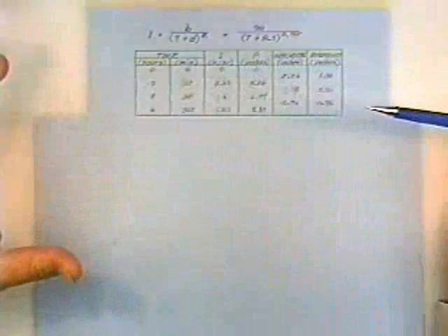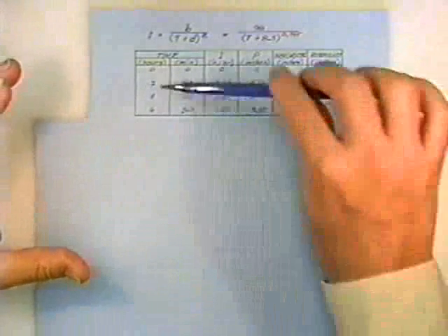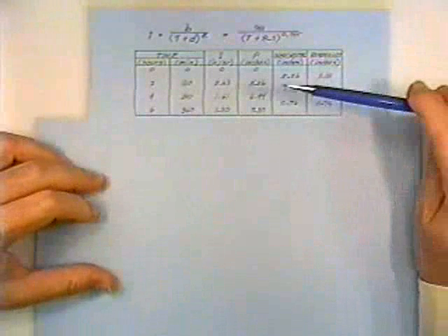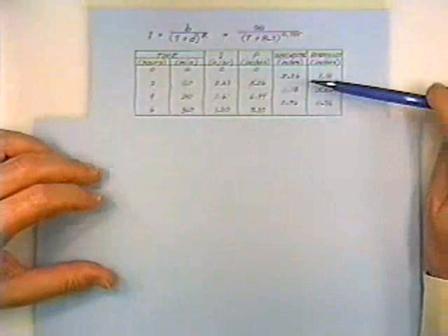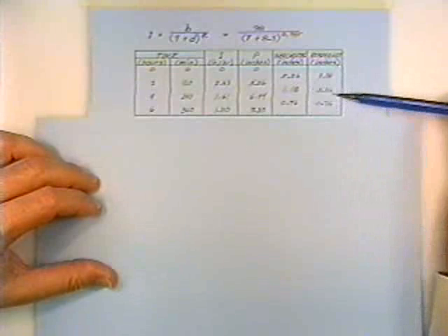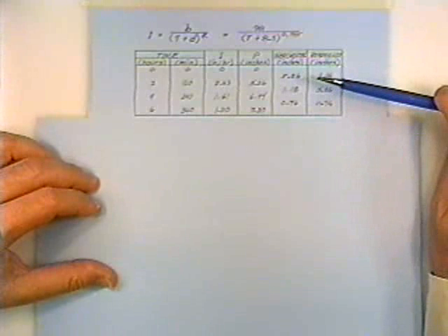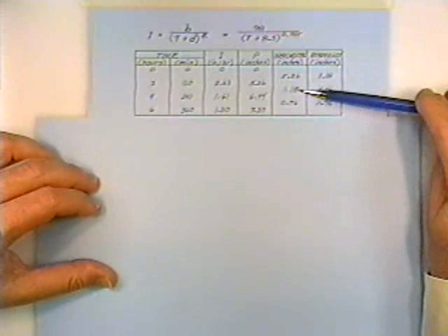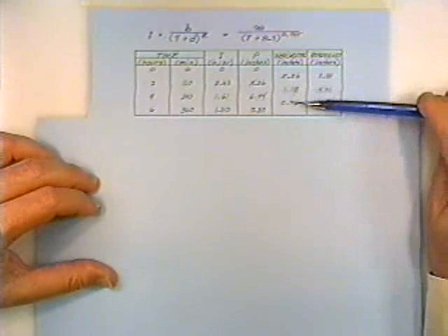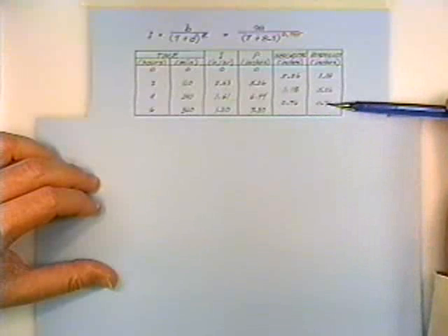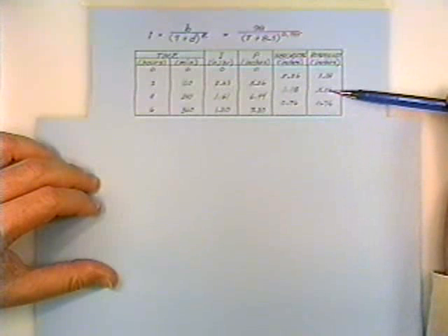So rainfall, the duration of a design storm is somewhat arbitrary. We're using 6 hours, somewhat in excess of the time of concentration of the watershed. Now, if it rains for 2 hours, you're going to get 5.2 inches of rain. So we're going to put that right in the middle, and then if it rains for 2 additional hours, you're going to pick up an additional 1.18 inches, and we'll put that there. And if it rains for 2 more hours, you're going to pick up an additional 0.76 inches, and we'll put that there. So we'll put the most intense 2 hours in the middle and less intense on either side.